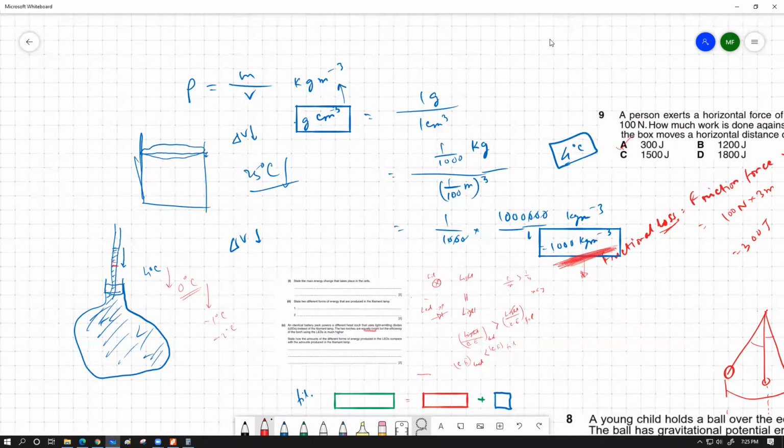So you just have to remember that water has a density of 1000 kg per meter cube. Whenever we use this term, in many cases we do not state that it was measured at 4 degrees Celsius. But you should know by heart that 1000 kg per meter cube is exclusively for pure water at 4 degrees Celsius. If you have impurities, it is going to be different, more or less. I cannot specifically tell you because different types of impurities affect it differently. And at any temperature other than 4 degrees Celsius, the volume is definitely going to be bigger. Whether you heat it up or cool it down, the volume of the water goes higher.